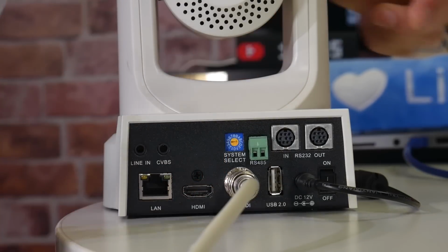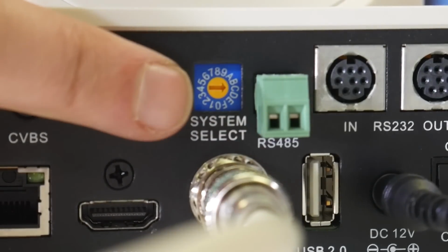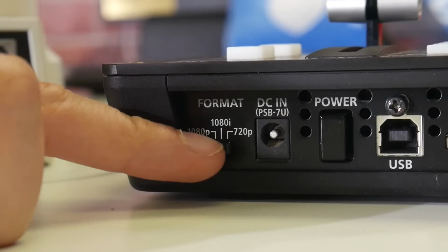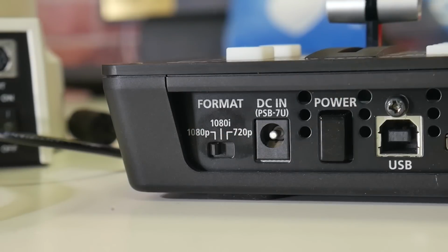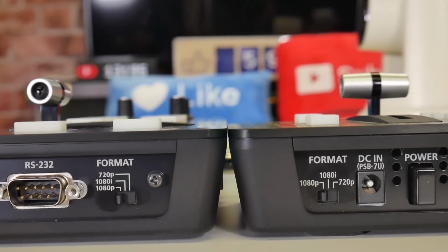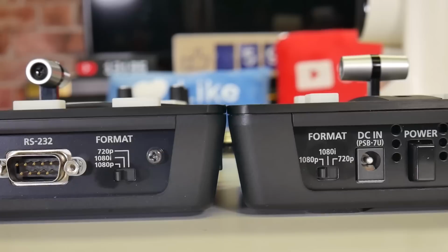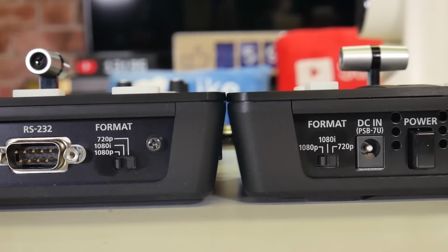We tested each of the resolutions for compatibility with the V1 SDI and V1 HDMI. Note, if you're using the V1 HD, there's a switch on the back panel to set up the switcher for either 1080p, 1080i, or 720p. Make sure to set this switch to the resolution type that you're going to be using before setup. On the V1 SDI, the switch is on the side panel.